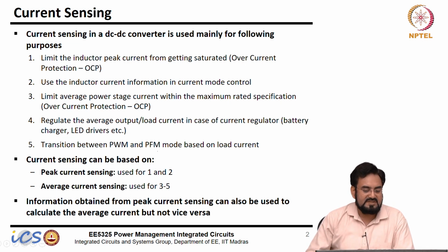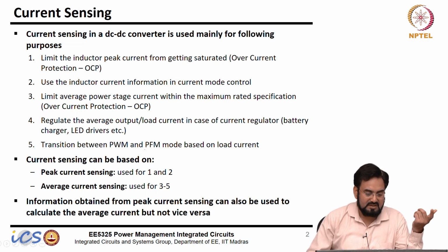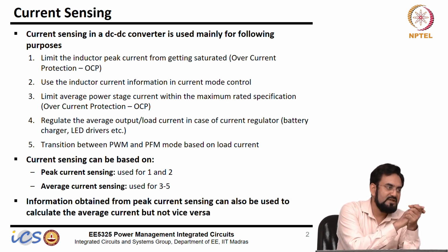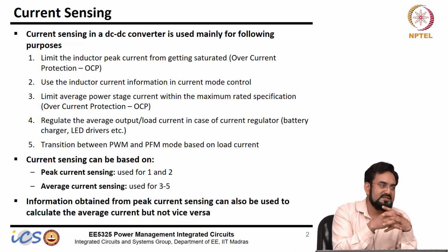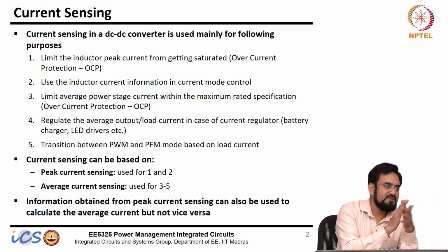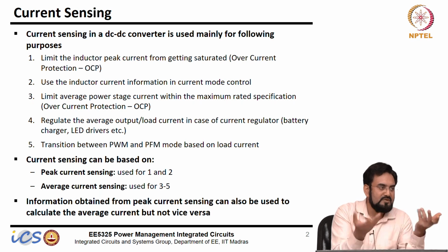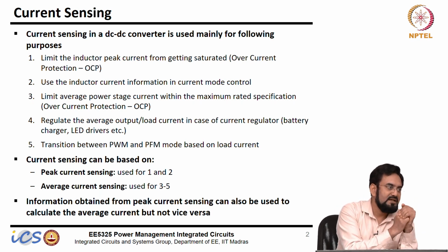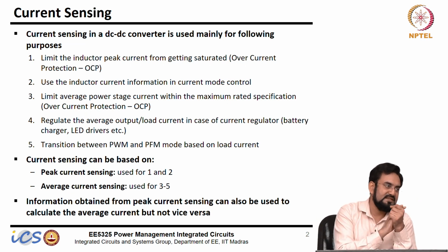Then another place which may or may not require it, depending on how you build your PFM mode. We talked about how you enter PFM mode. One is you can detect a light load condition, or you can always detect the DCM mode and right away when you enter the DCM mode you can enter PFM mode, or you can wait until your duty cycle is saturated. These two do not require current information. You know when the duty cycle is saturated, and you also know when it's entering DCM.